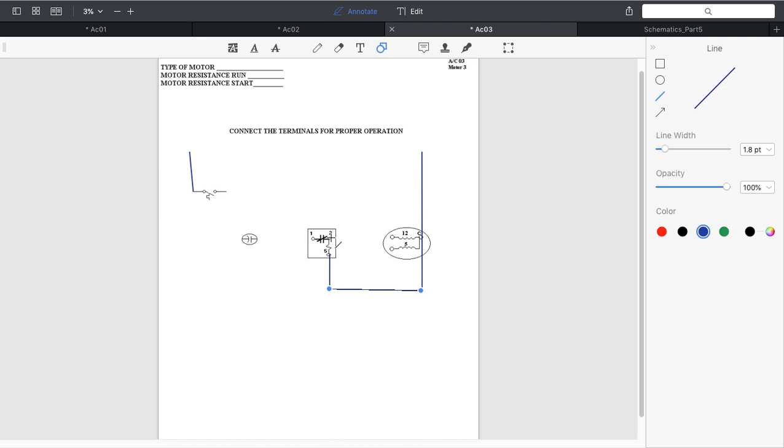Okay, pin 2 we know connects to our start winding. Might as well put that in. Our capacitor connects to pin 1, and our thermostat connects to our capacitor. Now we have one winding that doesn't have anything on it. Unfortunately, this one's going to end up jumping.